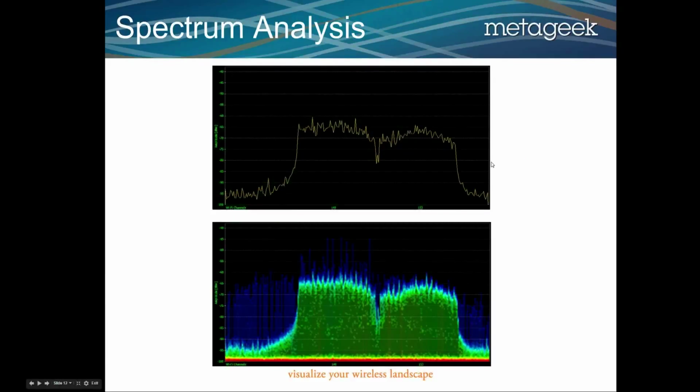Okay, so before we get into the live demonstration, I just want to talk about what a spectrum analyzer is doing. It's very similar to that yellow bouncing line that helps you visualize what music looks like. So if you look here, we have this yellow bouncing line. In the center, we see that it's loud, and on the sides, we see that it's quiet. So we know that something is transmitting right around, let's say, Wi-Fi channels 149 and 153. Now, our tool visualizes it in terms of how constant this yellow bouncing line is. So when you see that it's green here, we see that it is somewhat constant.